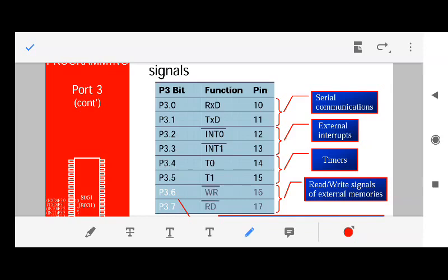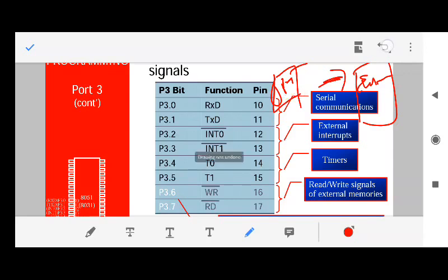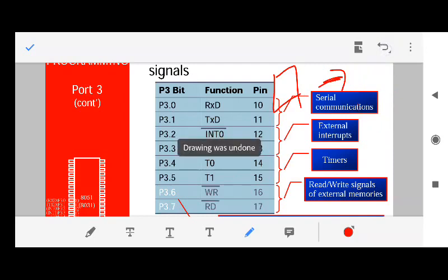But what if you wanted to write a large program? Because programs are saved in ROM itself. If you wanted to write a large program, in that case you have to attach an external memory to 8051. Fine. This is similar to attaching an external card to your mobile phone. So if 8051 wanted to have a large memory for a program, external memory has to be attached to it.